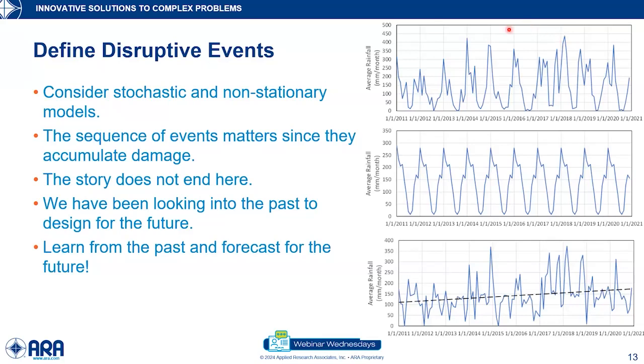So you typically, in the old-fashioned design where you have a deterministic design approach, you just define the peak. And in here, we're talking about rainfall. Rainfall can have a transfer function to the water table, and then it can give you basically the impact on an embankment, let's say, given the loads applied on it. And then you try to determine the peaks, and from that peak, you design for the most probable or expected peak value to make sure that your asset doesn't fall below that.